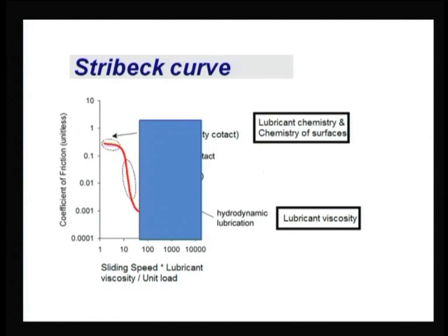If I see the other side, the left hand side of this line, if I do not consider the right hand side, now consider only the left hand side. Now, if in this case heat generation is high, temperature is high, and because of that viscosity is decreasing. Decrease in the viscosity will reduce the bearing number. If the bearing number is decreased, this is going to further increase the coefficient of friction. Increase in the coefficient of friction will increase heat generation. Increase in heat generation will increase temperature, that will reduce viscosity. So, this is a compounded effect.